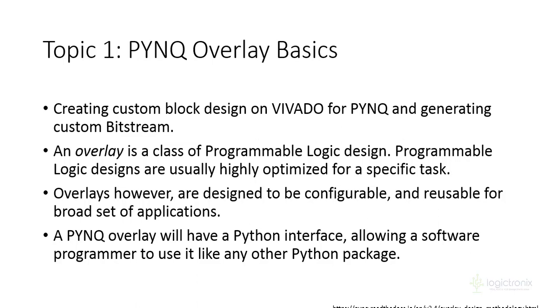Basically an overlay is a custom type of design, or any type of design, which is implementable on programmable logic. You are familiar with the PYNQ FPGA architecture. PYNQ FPGA consists of a processing system and programmable logic. If we want to implement any design on programmable logic, then that can be called an overlay. The overlay configures the necessary blocks and a set of GPIOs, and we can call that overlay with the Jupyter interface, and we can instantiate, set or configure the overlay as per our requirement.